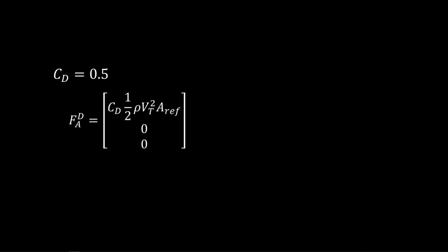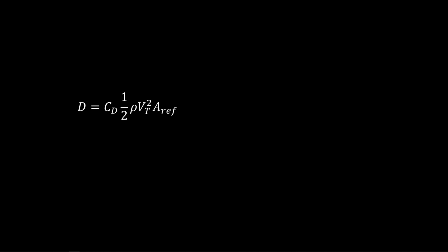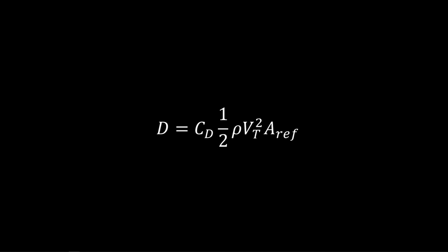From the drag force expression, we identified several variables necessary to dimensionalize the drag coefficient into a drag force. This equation captures changes in aerodynamic force due to changes in air density as a function of altitude. Also, if we're flying through a jet stream, there could be winds, headwind, tailwind, that could affect the airspeed term. For now, we don't consider such winds as part of our atmospheric model, but we will capture how air density and other atmospheric properties change with altitude.